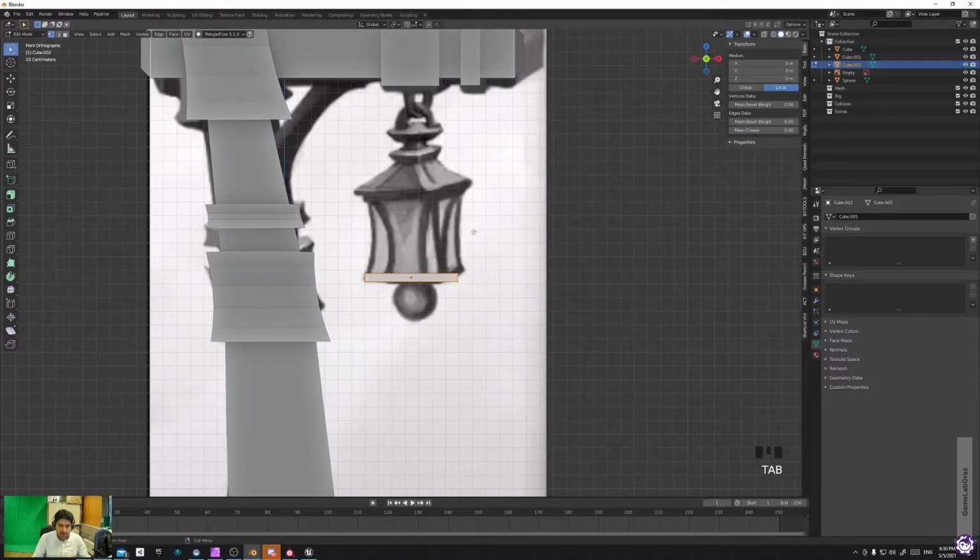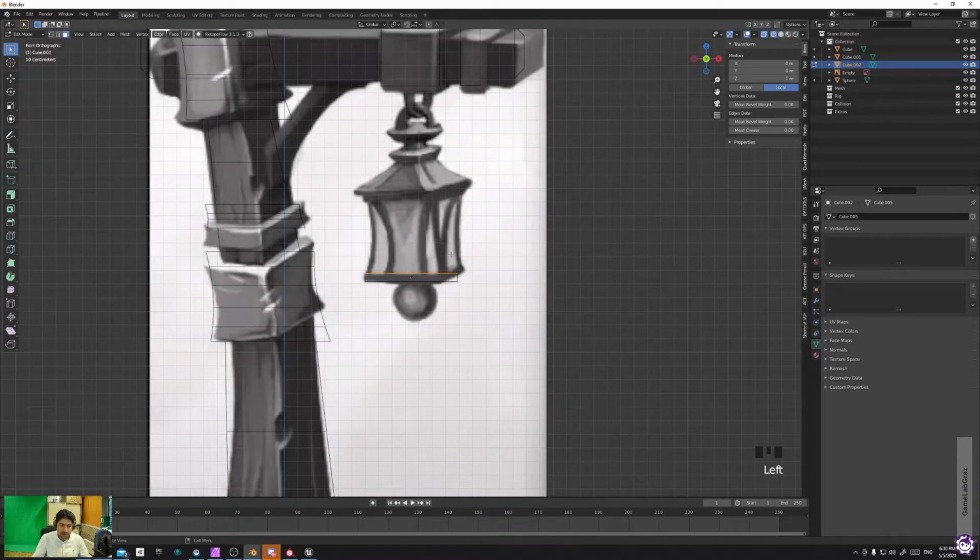Okay, we have this shape and we would like to reach the higher elevation of it. Absolutely, we can select each edge. So for now, I just move it a little bit up to this point, then extrude it and scale at the same time to go a little bit outward. Again, extrude, scale, extrude, and now we would like to reach that point.